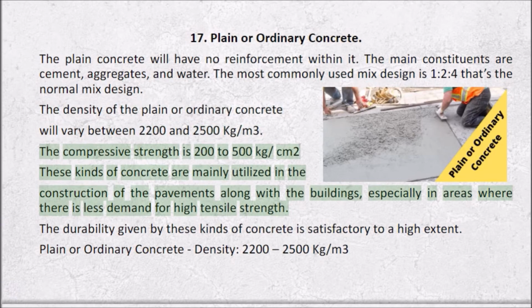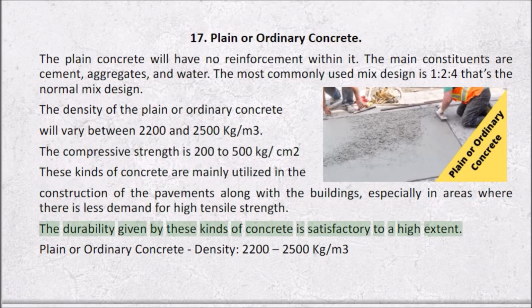The compressive strength is 200 to 500 kg/cm2. These kinds of concrete are mainly utilized in the construction of the pavements along with the buildings, especially in areas where there is less demand for high tensile strength. The durability given by these kinds of concrete is satisfactory to a high extent.